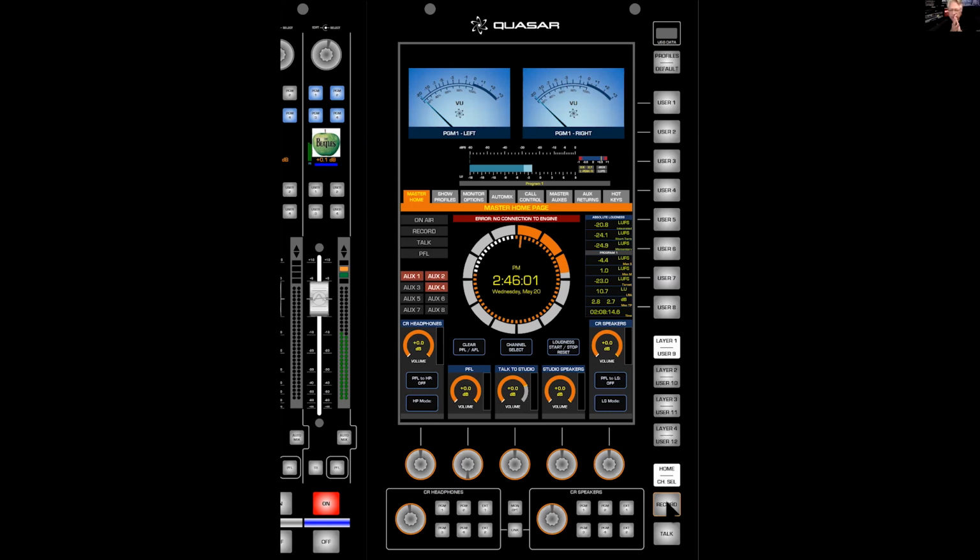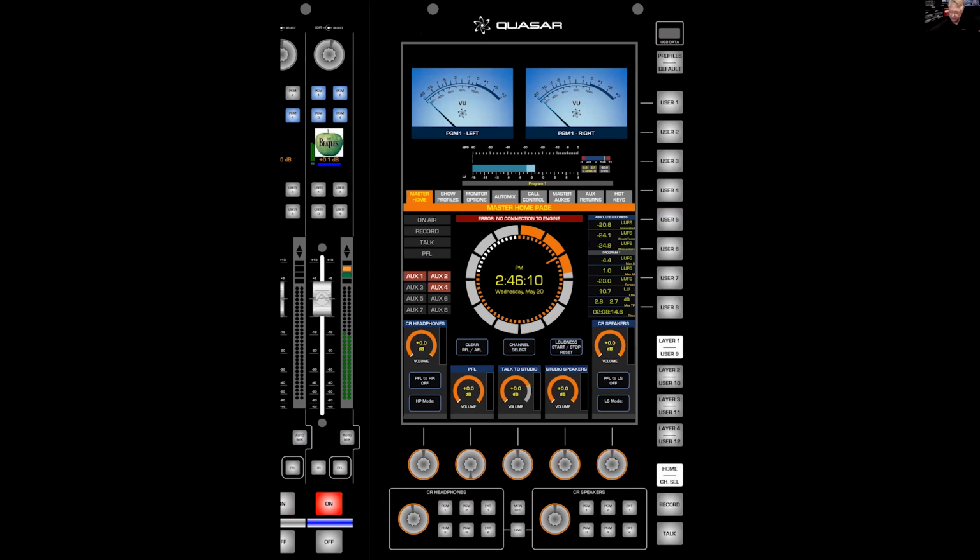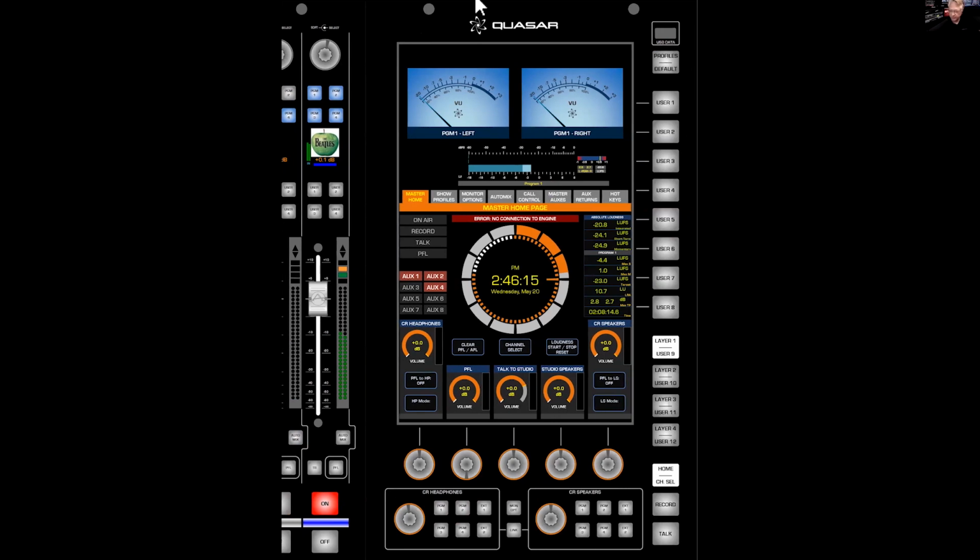So Cam, without the record button, a user would have to perhaps deassign their mic channel from program 1 and put other things into different buses, then change their headphone monitor, then record their voice track, all the while the console is still maintaining whatever's on the air. And then when they get done with that, then they have to go reassign all the stuff back to the way it was. The record button makes all that happen automatically. Exactly. It's just a very quick switching between 2 presets. Say it's a recording preset and an on-air preset.